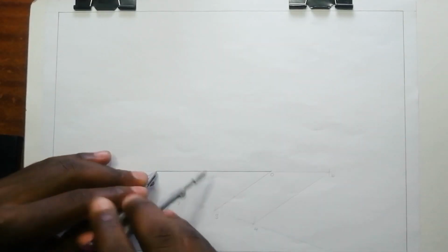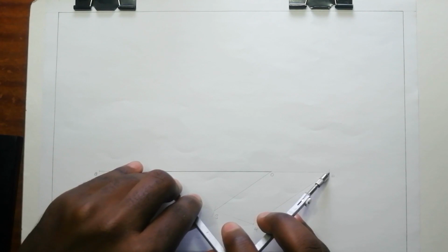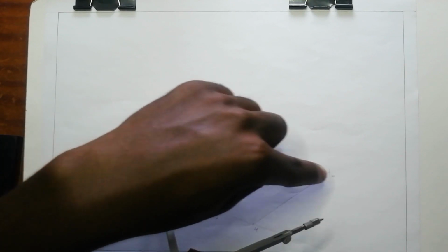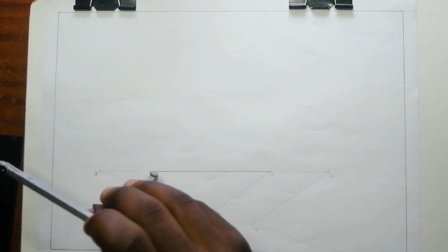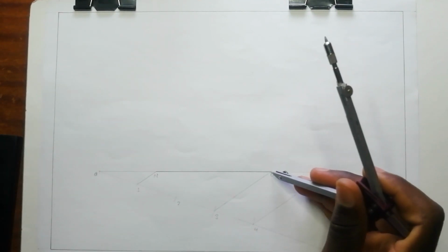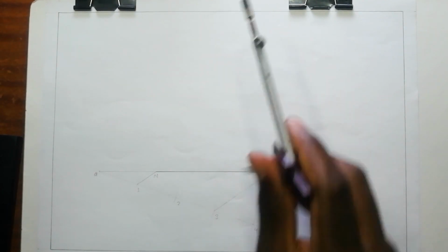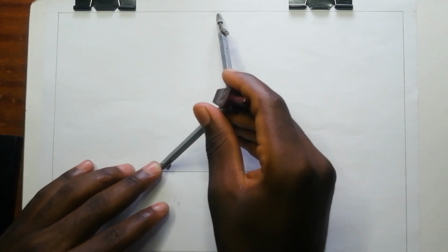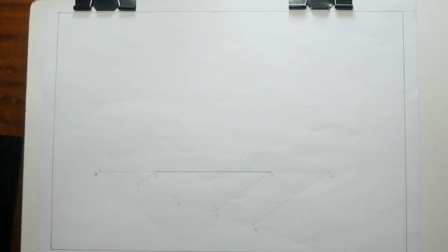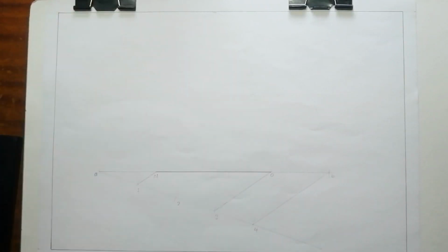We stand at N and then open to the side opposite, which is B there, not this one here, B. We strike an arc and then we go to point O, we do the same and we strike an arc. I'm very lucky here, my point P is just at the border. This shouldn't be the case when you're drawing. Don't really enter into that border, but I'm lucky it's just before the border.